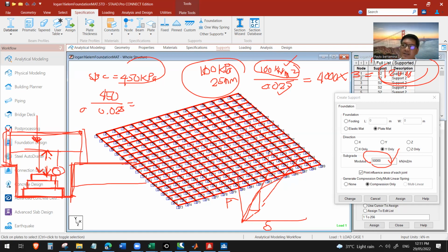using soil tests. There are correlations for medium dense sand, clay, and silt. Others use the cone penetration test, which is also possible. But at least with this plate load test, you are applying an actual load, in kPa. So for me that's more standard. It has an ASTM standard.